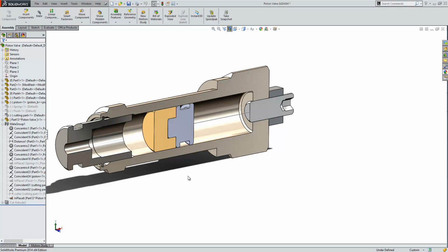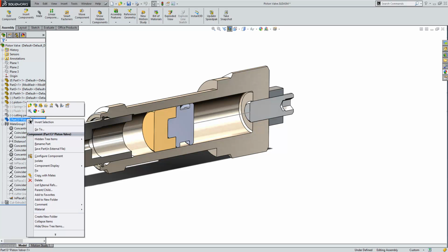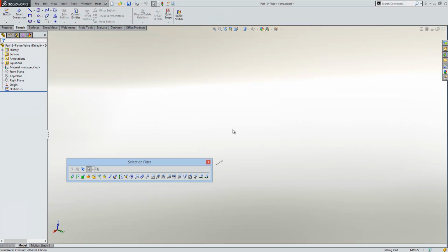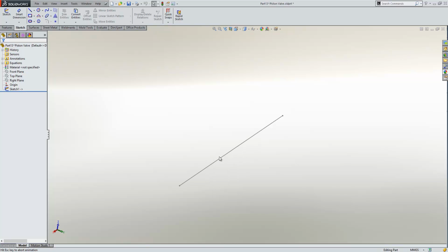So we've already got the behaviour that we want at sketch level, which is great, so we can move on to the next stage. I'm just going to query a dimension here first so we can see the radius of that circle is 6 mil, so diameter 12. So I really need to create something on the inside there to form my spring. So I'm going to open this component in its own window, and if we just zoom in and take a look, we've got our sketch on the screen like so.